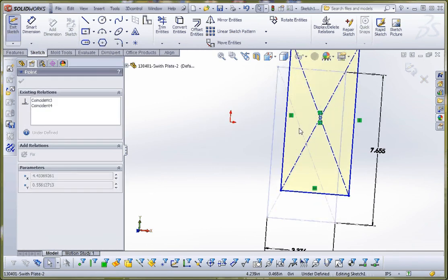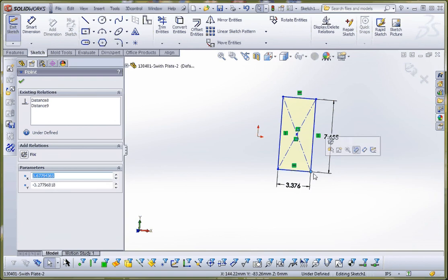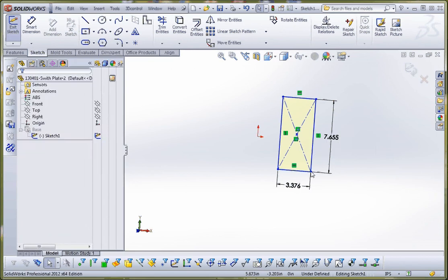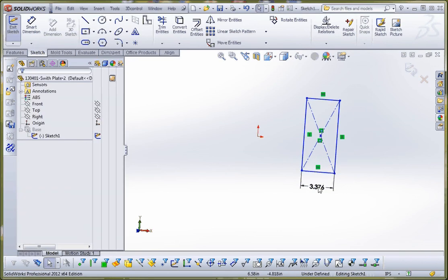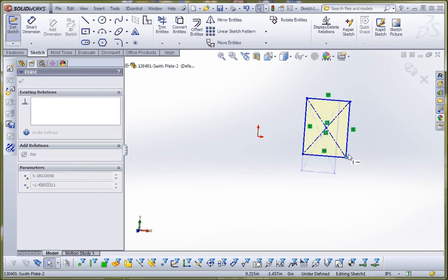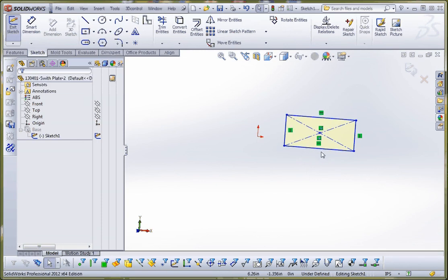We could take that rectangle, it's got a whole lot of flexibility to it. That means, because the lines are blue, and because we have the dimensions on here, we can't really stretch it. But it does have the ability to move around. We can take these dimensions to delete it, and now we have the ability to stretch it, and mold it, and move it around. And if we were to take off some of these other sketch relationships in here, we can actually get even more flexibility.